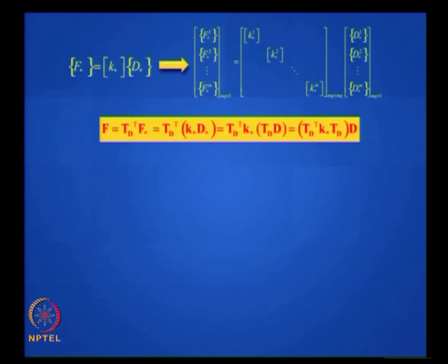So you have a similar transformation here. You see, you get the same structure stiffness matrix from the displacement transformation matrix in this manner. So let's say you get Td, let's say you got K star, you got K by this method, and if you don't want to do it for the whole structure, you want to do it element by element, that's also fine, but then you have to sum up for all the elements.